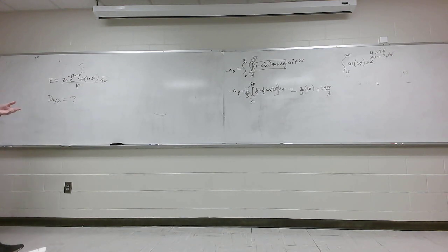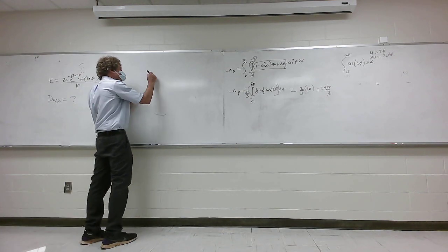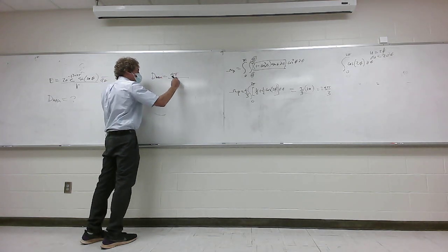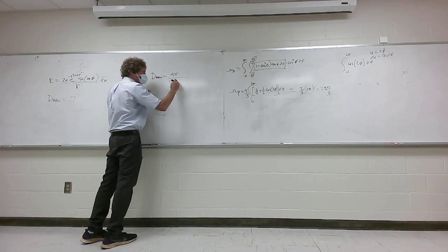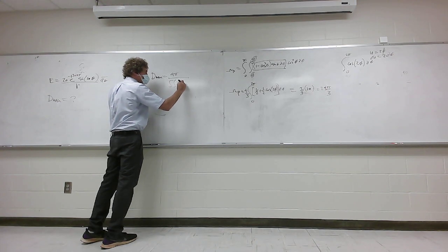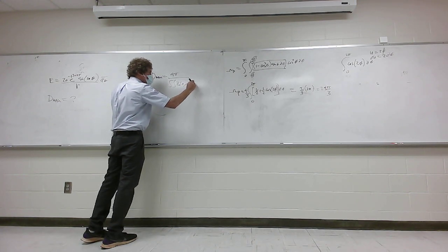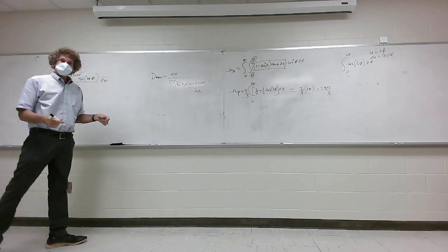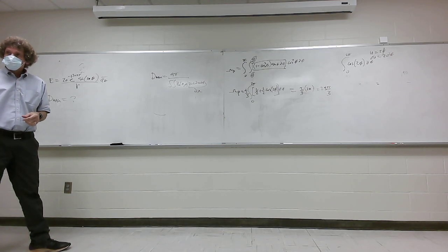Well, what does D max require? 4 pi over that integral of what? Normalized power density, sine theta d theta d phi, right? This is often termed d omega, but you don't need to know. Do you all agree with that? Everybody hear me now?